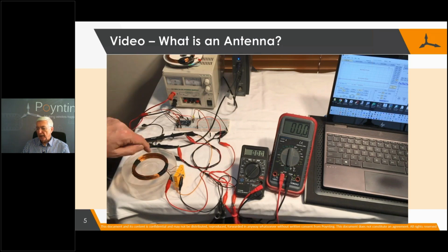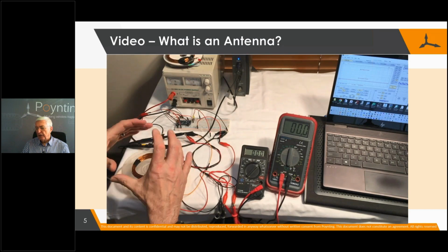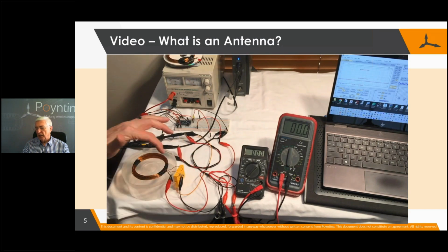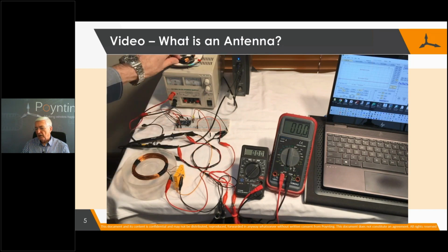That's going to be the electrical component of our transmitting antenna. On this, that is going to create the electromagnetic field that our receiving antenna is going to get. That is the little oscillator that creates an alternating current. And then in the back there I've got another 50 turns of enameled copper wire.